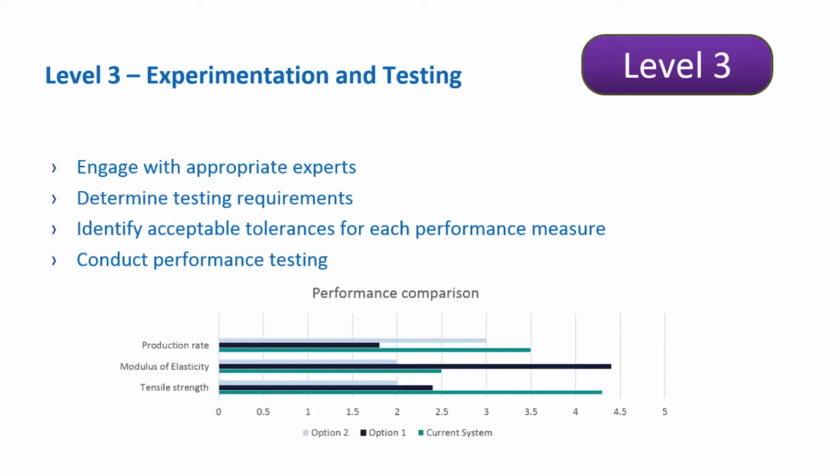Use your functional use and performance or quality requirements identified and establish a performance scale for each. The scale can be quantitative or qualitative depending on the measure. Use relevant performance standards or specifications. Determine what are acceptable tolerances related to each performance measure and conduct the relevant performance tests. Working with a coalition of similar companies in this research may be helpful in these cases.